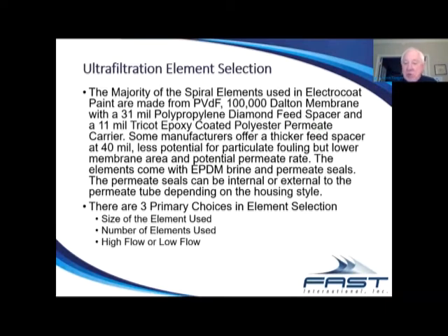There are some manufacturers that manufacture it with a thicker feed carrier of around 40-45 mils. That is sometimes less potential for particulate fouling in that feed spacer, but it does reduce the membrane area and has the potential for a lower permeate rate.